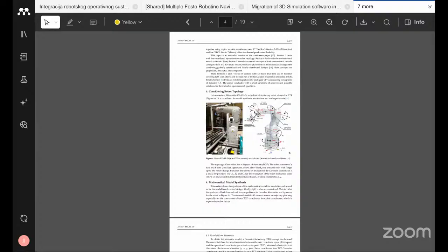Initially, the robot links will be considered as ideal rigid bodies. That means the robot arms will not bend or change shape. The kinematic model does not consider force or torque, only position, orientation, and velocity. The relationship between position, orientation, and velocity is called the kinematic model.